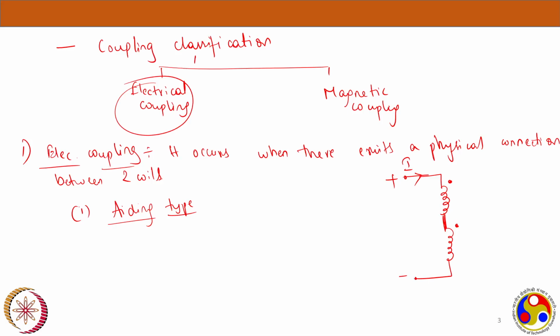That is the first definition we have seen, where we say a coil is coupled if there exists a mutual inductance between them. Between these two coils, apart from their self-inductance, there exists a mutual inductance, which we call M, and they also have their self-inductances L1 and L2.